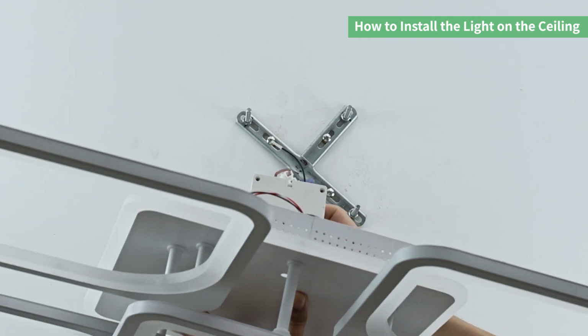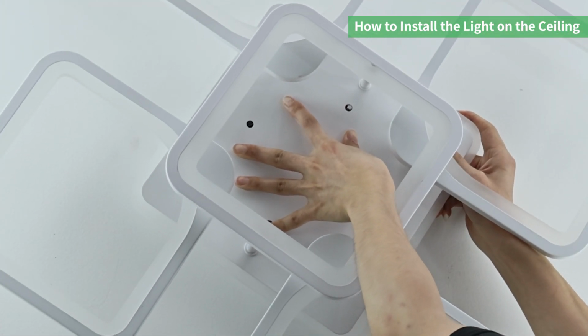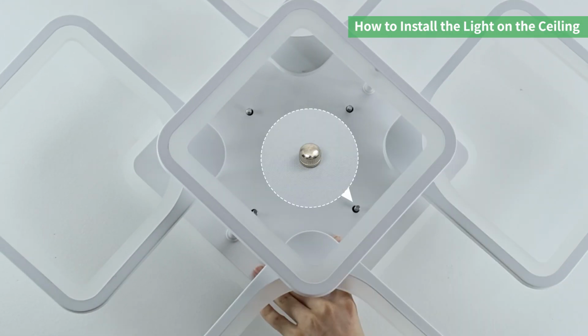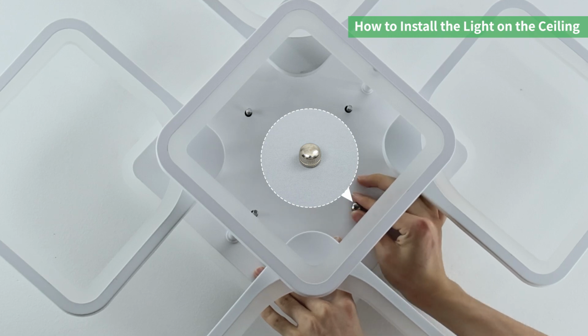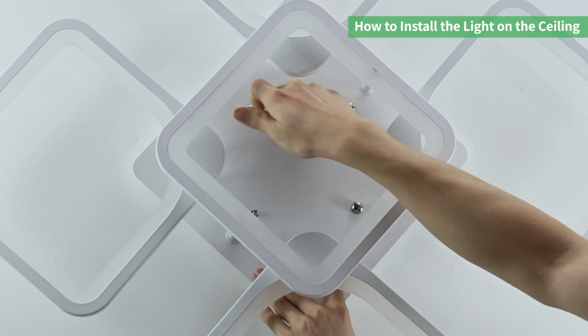Install the entire light fixture on the ceiling, allowing the screws of the cross bracket to pass through the holes in the lamp base. Use nuts to secure the screws to the lamp base, tightening them to ensure that the light fixture is completely fixed to the ceiling.